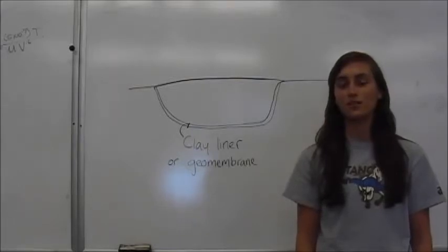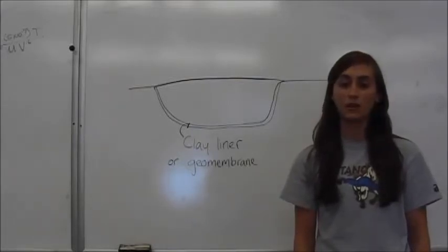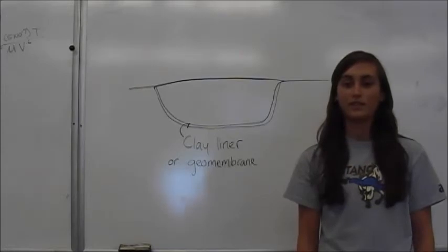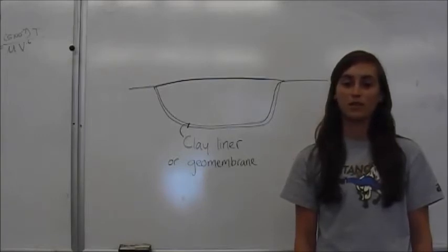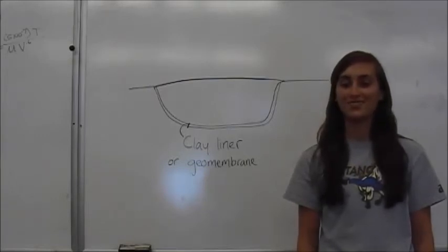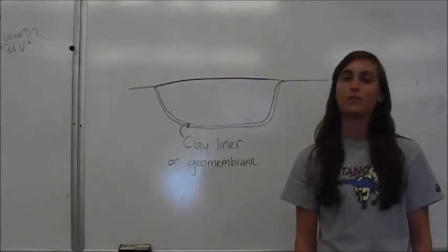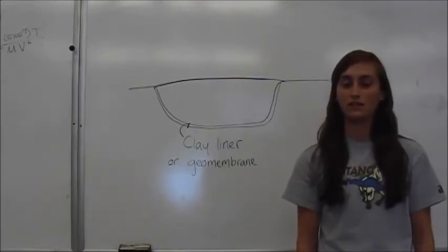Another way the diffusion coefficient is used is in groundwater contamination. It is needed when finding how far a contaminant has spread. The movement of a pollutant in groundwater, called hydrodynamic dispersion, includes molecular diffusion, in which case you'll need the diffusivity constant, also the velocity of the water, and the turbulence and mixing.